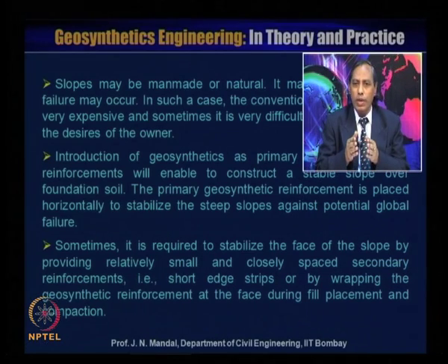Sometimes it is required to stabilize the face of the slope by providing relatively small and closely spaced secondary reinforcement. I will show you later what the secondary reinforcement is, how you can place the secondary reinforcement in a slope, and why it is required to introduce the secondary reinforcement along with the primary reinforcement along the facing of the slope.